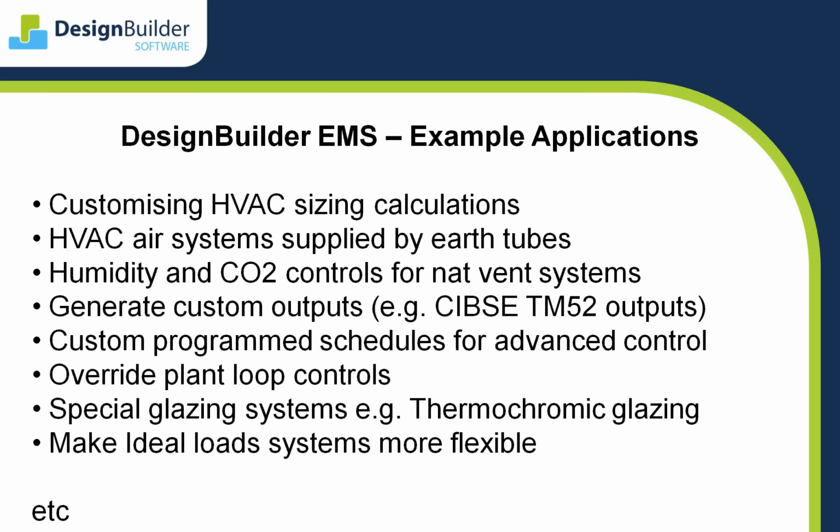Some example EMS applications are customizing the HVAC sizing calculations, supplying an air system via an earth loop, controlling natural ventilation systems on parameters such as CO2 or humidity, and modeling special glazing systems such as thermochromic. There are many uses for the EMS, and our program help contains much more detail.